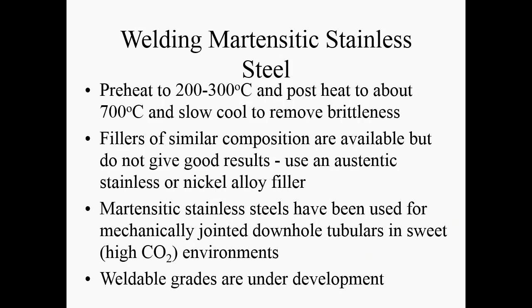Part of the reason it's not more widely used is there isn't a good weldable grade. They're getting better all the time, and every year I see a new development and somebody says it's going to solve all the problems, but then it disappears quite quietly. So it's never quite as good as they hoped it was going to be. And it's largely because of the very high carbon equivalent of the steels, the need to have all these pre and post weld heat treatments. You can make the pre-treatments not so aggressive, but they're still pretty bad compared to the plain carbon steel.